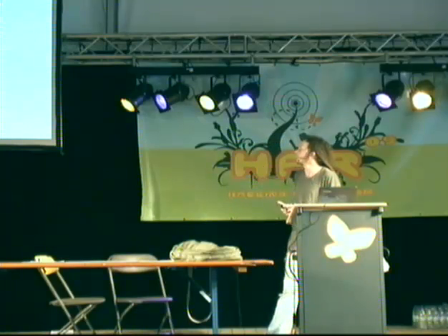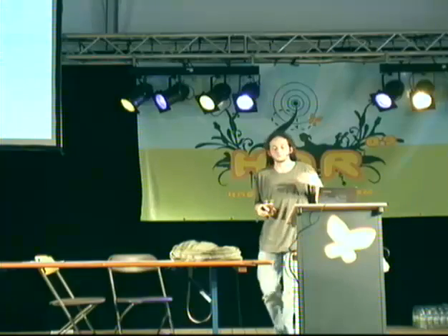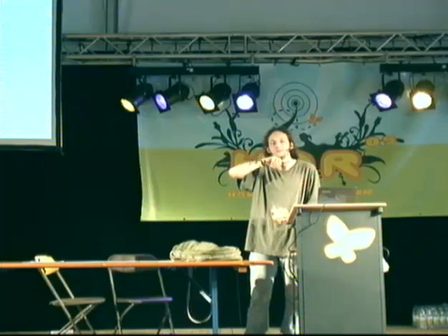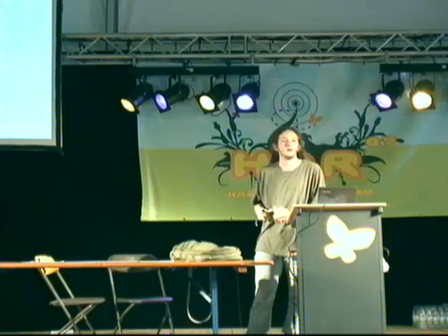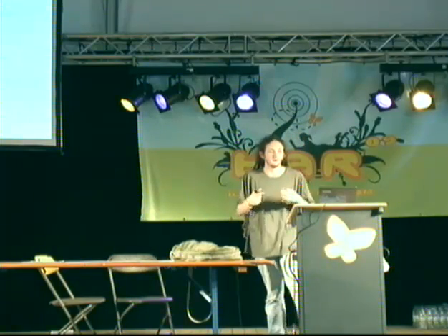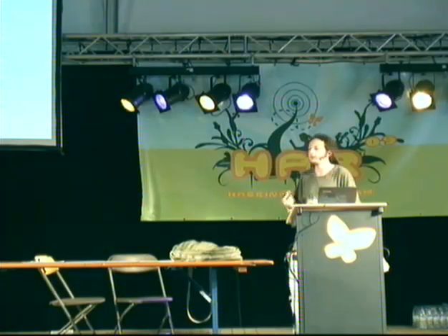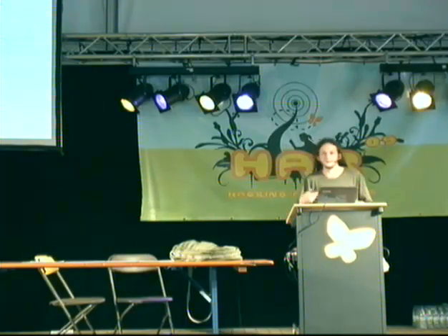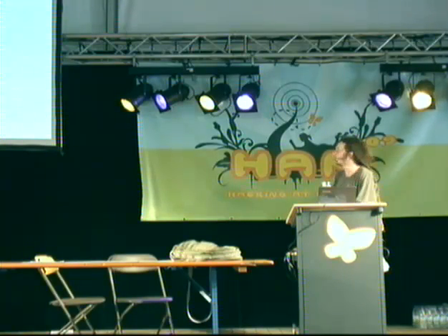So when I was attacking one of these with Aurélien Francione, we started sending random packets. And the random packets would have just repeated fields of the entry point of the bootloader. And then we just waited for the bootloader to start up and say hello. We could tell this because a certain I/O pin would become an input pin. Whenever we failed, it would just reset and we could get another try. And on the few cases where it locked up, we just hit the reset button. And this worked very quickly.